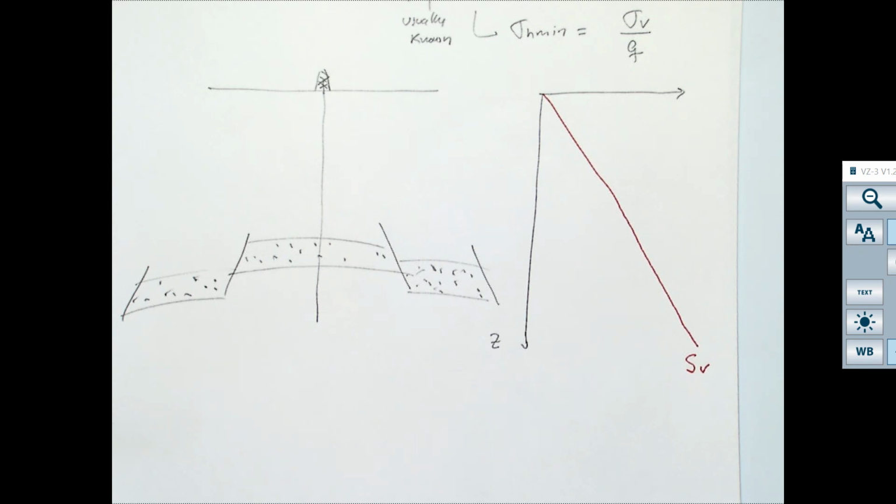I was asking for total horizontal stress, and many of you calculated effective horizontal stress. I underlined total because usually in the field we cannot measure effective stresses. We measure total stresses. So for that case, you needed to calculate the total horizontal stress.